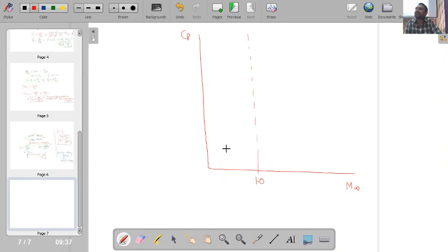So before this I will be having subsonic flow, and above this I will be having supersonic flow. Okay. So if you see, earlier we have the Prandtl-Glauert rule. From the Prandtl-Glauert rule, I see the value of Cp is inversely proportional to the square root of 1 minus M infinity squared. And here I have got Cp as inversely proportional to the square root of M infinity squared minus 1. So ultimately what will be happening in this region, when Mach number is increasing, the value of Cp will increase for the subsonic region.